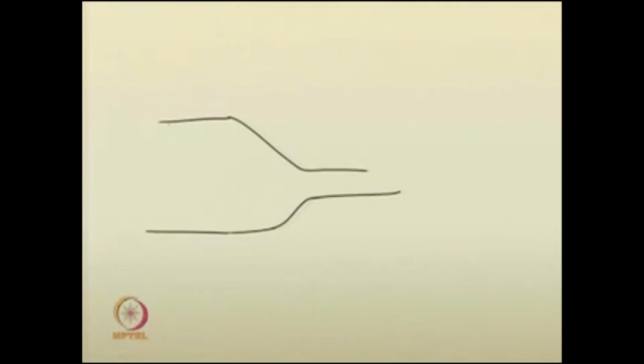Now, see, if the channel is getting restricted, here the channel width is 4 meters, and this is the critical width, we do not know what that value B c is. So, you have E 1 at the upstream section equal to y 1 plus q squared by 2 g y 1 squared.